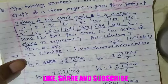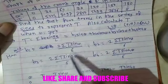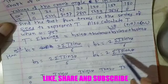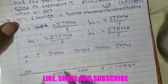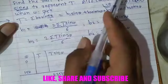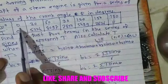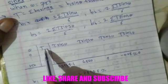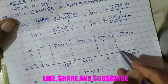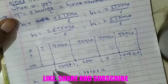So in our table, the first column is theta. After theta, the second column is t. Then for b1 we want t sin theta, for b2 t sin 2 theta, for b3 t sin 3 theta, and for b4 t sin 4 theta. So in the table, write down all values of theta. Theta starts from 0 to 180, but for 180 the value of t is given as 0 again, so take theta from 0 to 150 and write down the respective values of t here. Then find t into sin theta, t into sin 2 theta, t into sin 3 theta, t into sin 4 theta, and write down the summation of each column below that column.